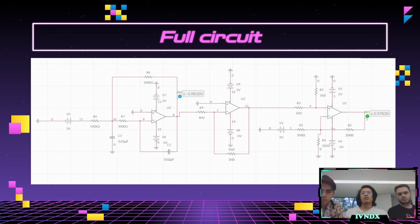In essence, it just subtracts 2 volts from the main voltage, giving us our -3 volts range, since it's still a linear response. We were able to complete the filter, and it filters frequencies above 50 hertz as it was required. And just to finish it up, we added the inverter.